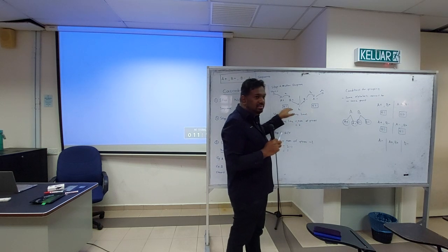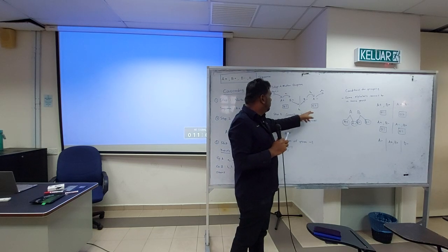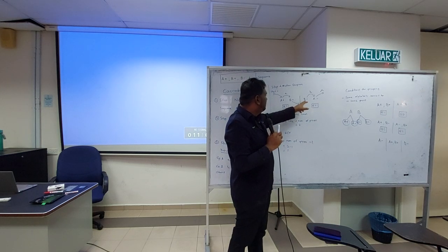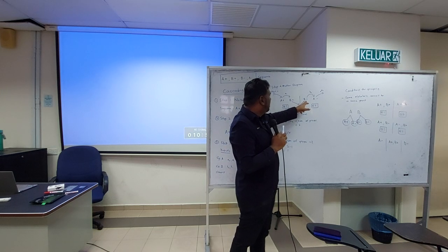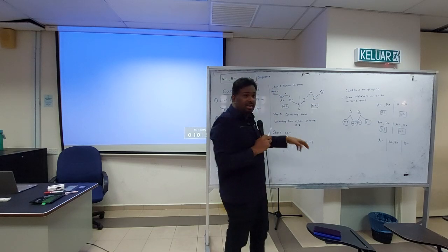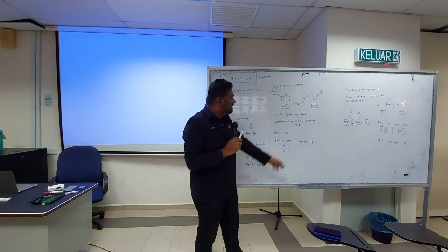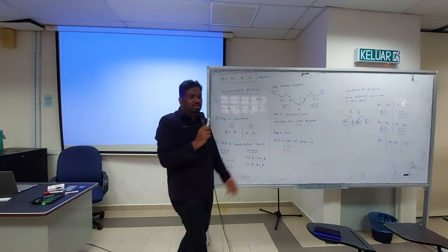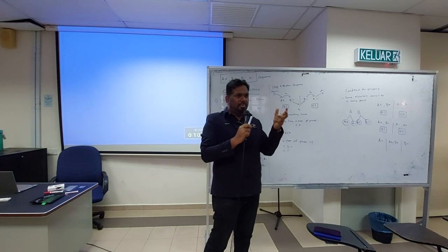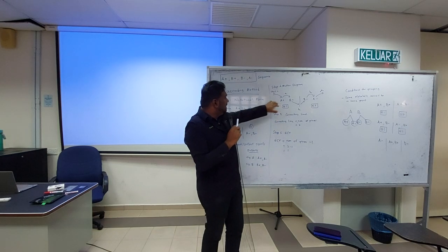The earlier line was G1, so it powered line G1. Here you change to group 2, so you need to activate the group changing valve with B1. B1 activates B minus, B minus activates B0, which activates A minus, and then the cycle is complete. So it only needs to change line once, compared to 3 times earlier. That's why grouping is very important. If you do not execute the grouping properly, it will cause a lot of confusion later.